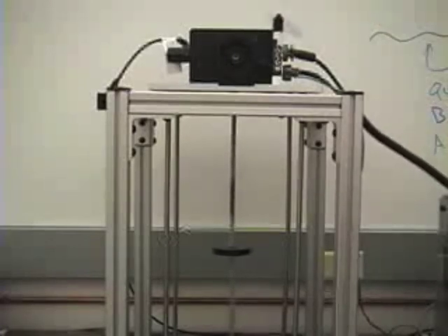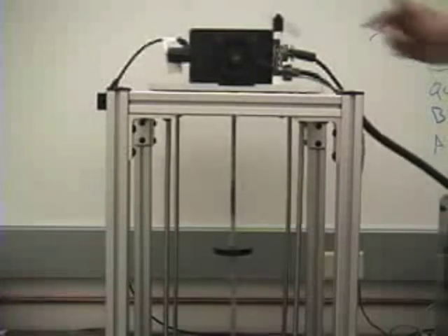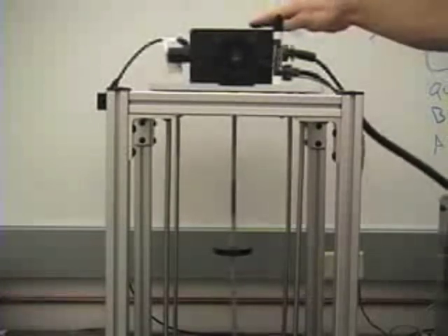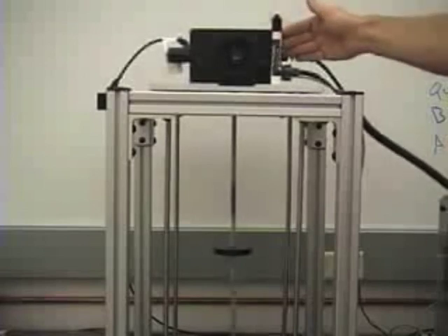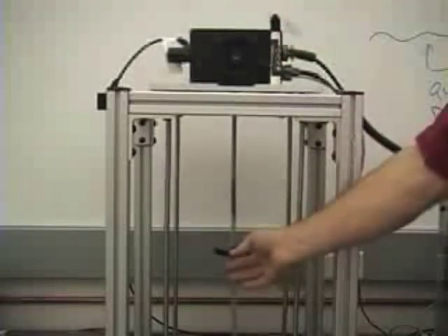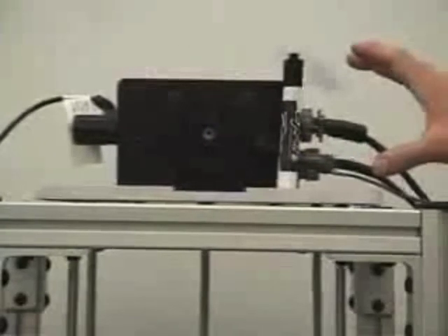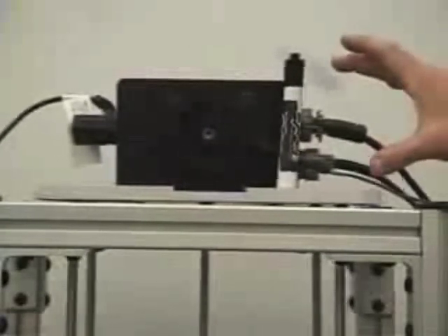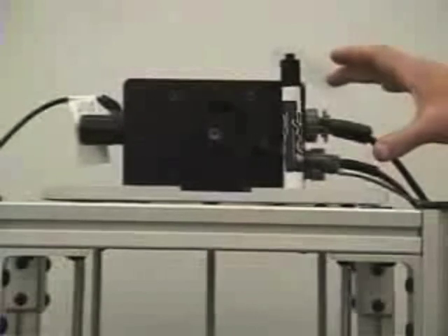If we spin it at a different speed, I'll adjust the speed now. Now you can see there's much more significant vibration at the top of this because we're no longer operating at the resonant frequency of the tuned mass damper. And here you can see we're very far away from the tuned frequency and we're getting significant vibrations of the building due to the imbalanced mass.